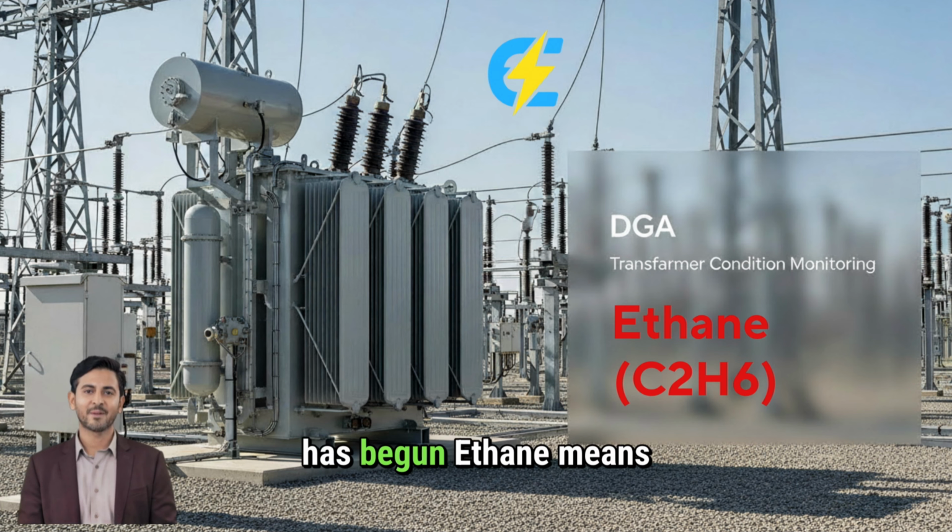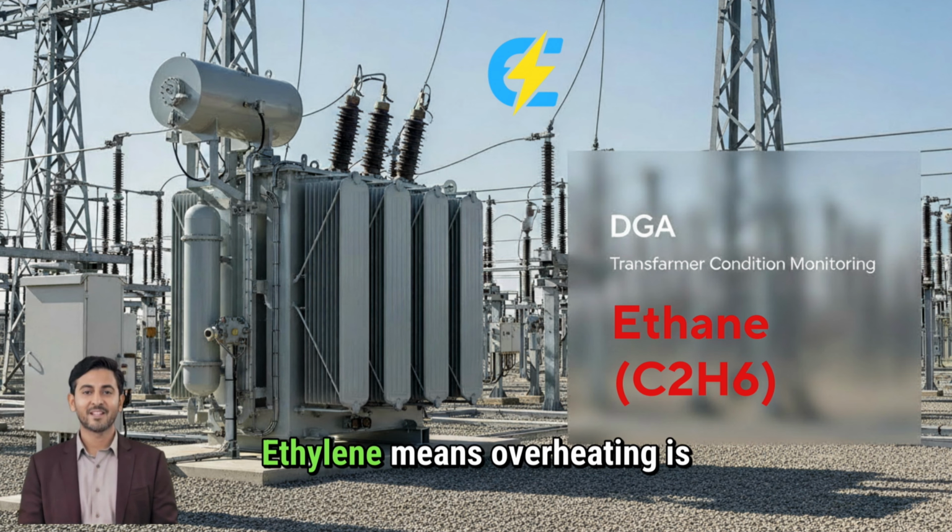Methane means the fault has begun. Ethane means the fault is evolving. Ethylene means overheating is accelerating.